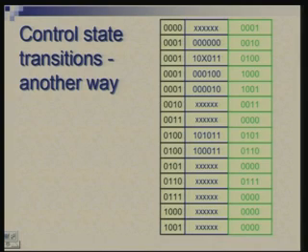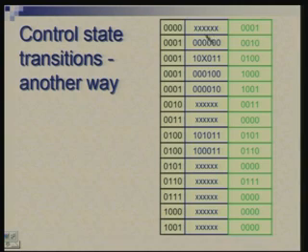a ROM. Okay. This will require 4 plus 6, which is 10 inputs. That means 2 raised to power 10 or 1024 words in the memory. Each word will be 4 bits, and total number of words will be 1024. But in PLA, you will have 1, 2, 3, 4, 5, 6, 7, 8, 9, 10, 11, 12, 13, 14 terms. Okay, so k will be 14 here, right.